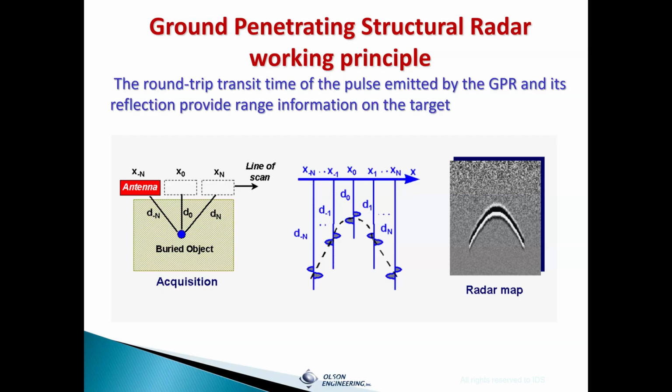So many of you are probably already familiar with ground penetrating radar, and Larry mentioned it a little bit just now, but just quickly going over some of the principles of it. It's particularly useful for locating buried objects, voids, in the case of regular reinforced concrete, rebar. Here's a quick schematic of how it works. On the left, an antenna emits electromagnetic pulses, and the pulses are reflected back off of changes in impedance caused by an object that's different than the surrounding materials.